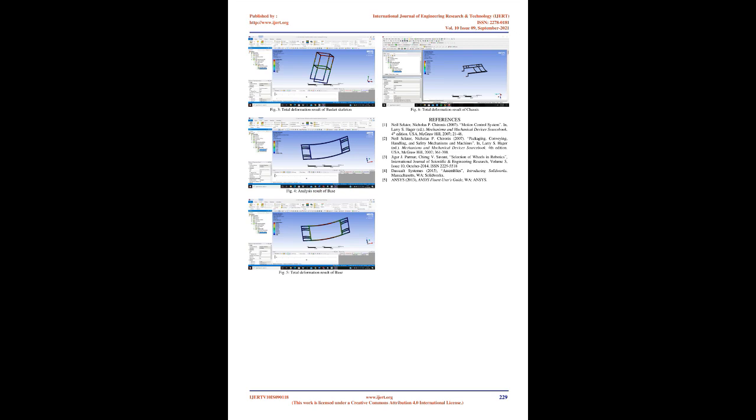RPM. Diameter equals 202 mm or 0.2 m. Circumference equals pi*d equals 0.63 m. Assuming velocity of rotor to be 1 m/s, RPM equals 1/0.63*60 equals 96 RPM.